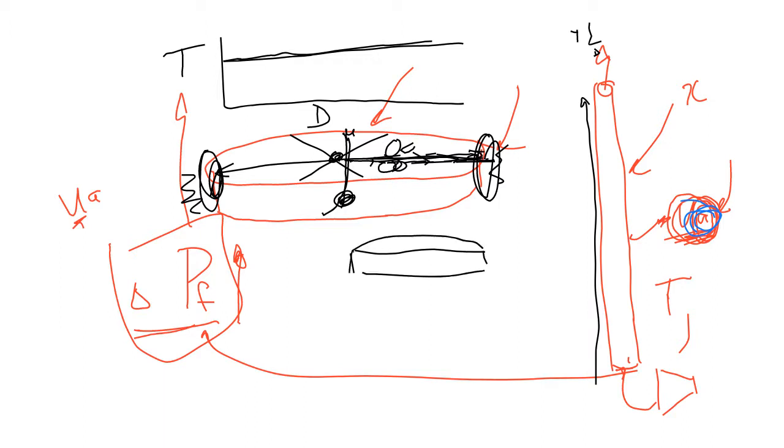Okay, that's a pancake there. You will not build pancake-like reactors because you will not ensure a constant radial temperature. If I have a reactor that's not exo- or endothermic at all, which doesn't happen, so if the ΔH of my reaction is pretty much 0, and I don't want heat transfer, or if I want to size an adiabatic reactor, so I don't care really about the heat transfer, then that pancake-like one will work in that respect.